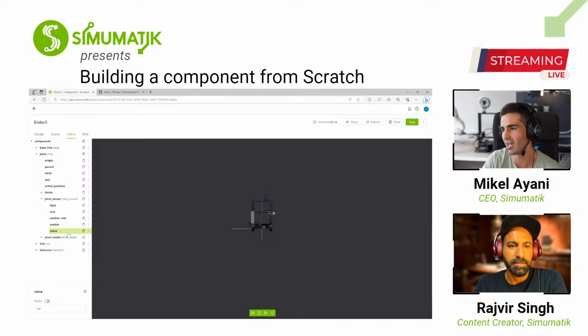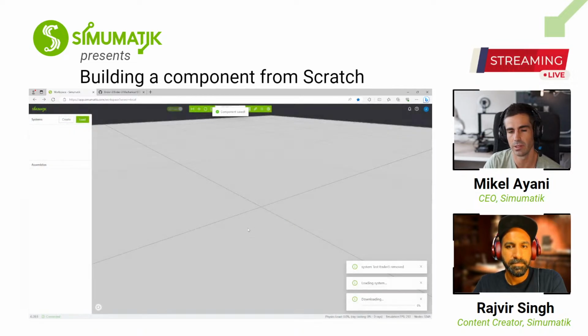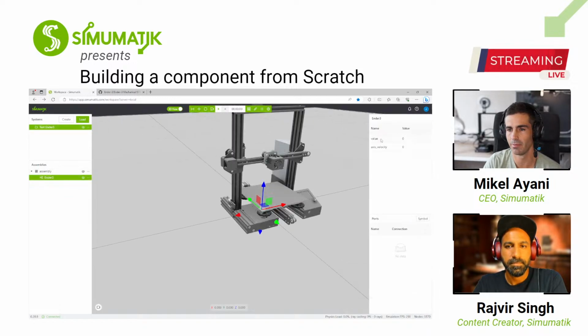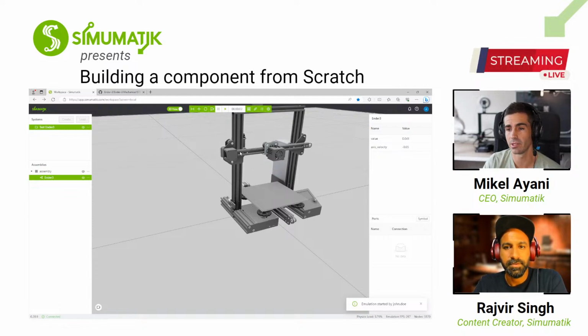So here basically we have the value. We could make this public directly if we don't want to use it for anything in the behavior. Save, and hopefully if we go back, we reload. Now when we click here, we should see the value. Of course, the name is not good, but this is the value of the sensor. And now when we go up or down, we see the position in meters. That's very cool. This is so useful to take feedback from the linear drives. So it stops at minus 0.1, and it should stop at the top level, which is 0.15.